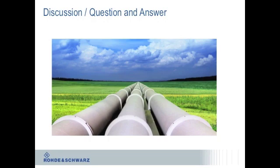And what happens is, if you think of them as constellations, think of an XY coordinate plane and all these little dots, and each dot represents a state. What you would like to do is to have your signal fall neatly onto one of those points to represent one of those states. In the real world, that doesn't always happen. As a matter of fact, it pretty much never happens. The points don't exactly fall on the ideal point, so they're a certain distance away. They're a certain X and Y away. And the distance that they are away, the vector, the error vector magnitude, in other words, how far that is, is what EVM is. How far away is this particular point from the ideal point in this constellation?